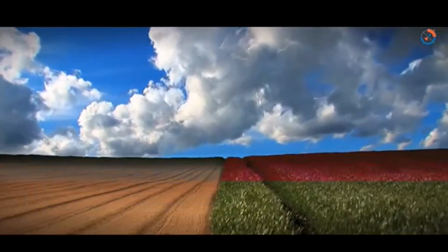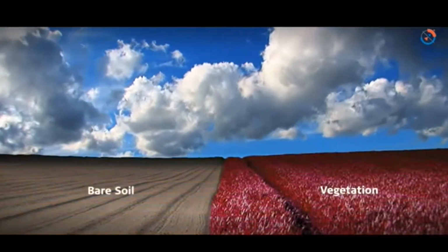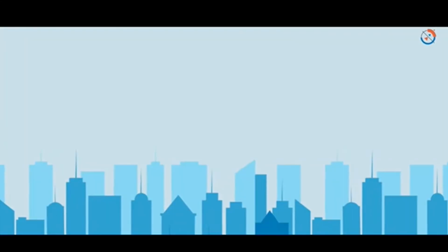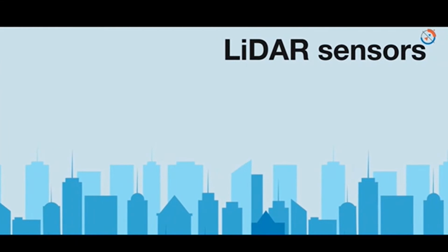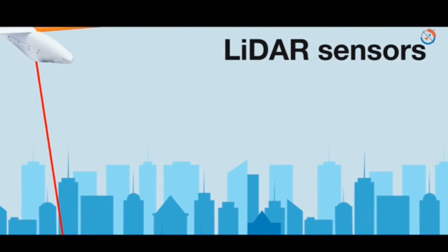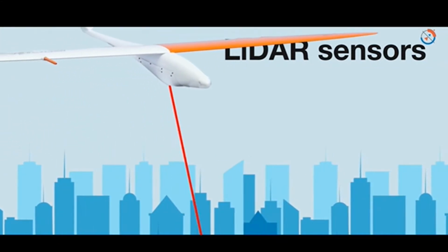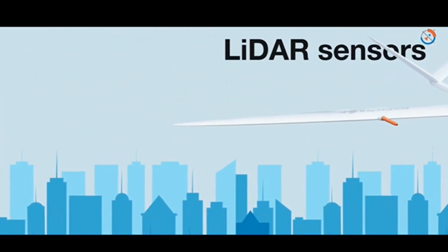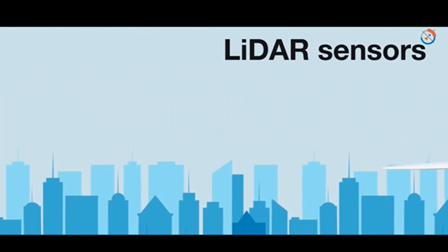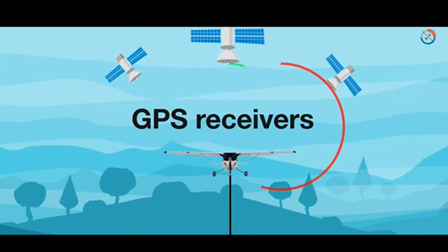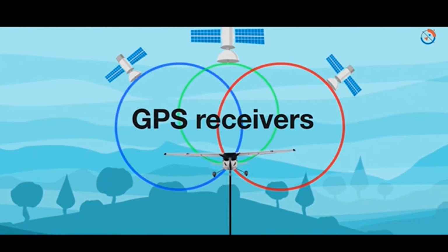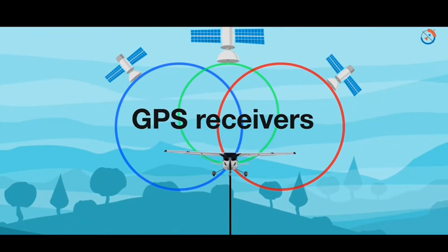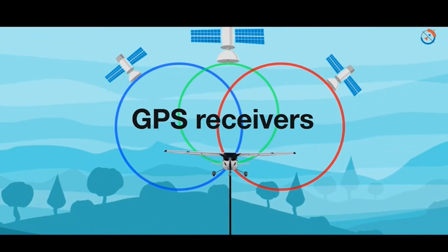How does a light detection and ranging system work? There are four parts of an airborne LiDAR. LiDAR sensors scan the ground from side to side with a pulsed laser beam as the plane flies. The sensor has a detector for sensing the returns from objects. GPS receivers track the altitude and location of the airplane. These variables are important in attaining accurate terrain elevation values.